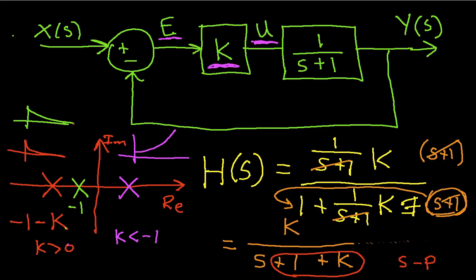For most physical systems, you have some upper limits on either the amount of voltage or the amount of force or whatever the input to the system is. You may have upper limits on how big that can be. And by making the gain large, we get this situation where the system responds quickly, but it responds quickly because the magnitude of the input has been made very large. And sometimes that may be a bad thing.